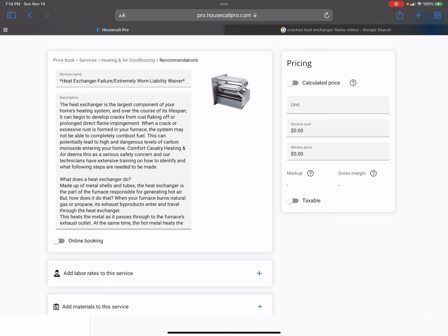So maybe you check with your analyzer, you test the carbon monoxide in the supply ductwork, and there is none there yet. But then you check the exhaust flue pipes, and there's a minimal amount. Okay, that still doesn't mean everything's good to go, right? I mean, if you have flame impingement, that little bit coming out of the exhaust may be less than, in our case, 100 parts per million, we let it go.